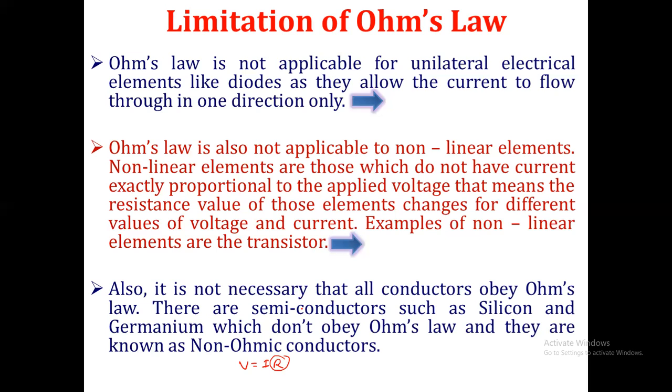Please read all the limitations once. Let me try to read along with you. Ohm's law is not applicable for unilateral electrical elements like a diode, as they allow the current to flow in one direction only. Second, Ohm's law is also not applicable for non-linear elements. Non-linear elements are those in which the current is not exactly proportional to the applied voltage. That means the resistance values of those elements change for different values of voltage and current. For example, a transistor.